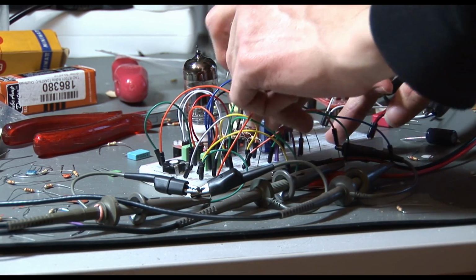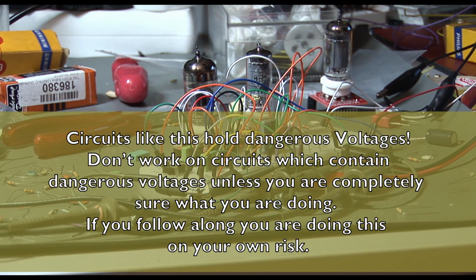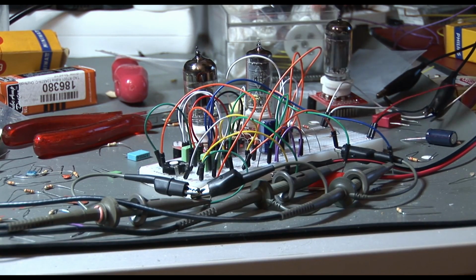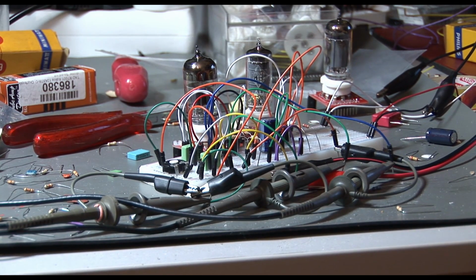One note is that this thing is now actually not acting as a current source. It's actually acting as a current sink because it draws current in. A source would give current out, but this thing is a current sink because it draws current. The load is above the current sink, so therefore it's a current sink. If it were a current source, then the load would actually be below the current source. So this is actually a current sink, but just so that you have heard it.